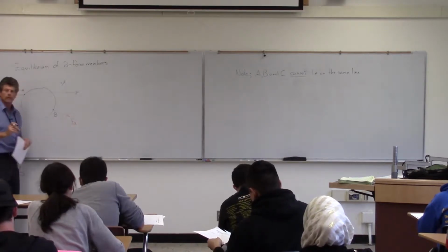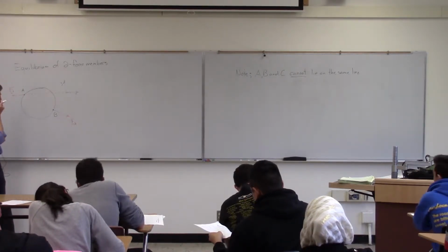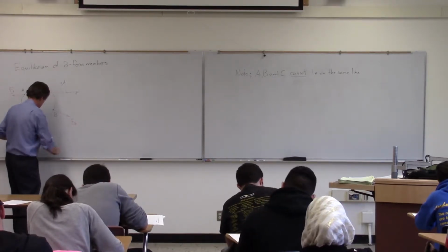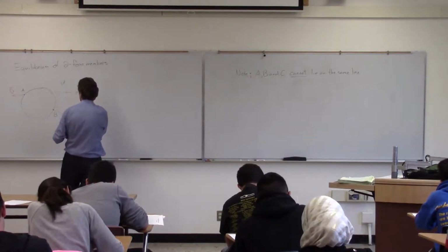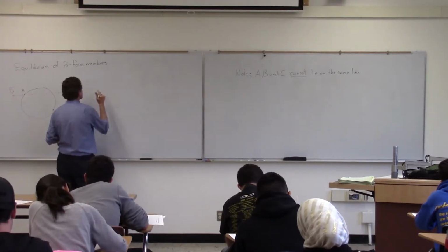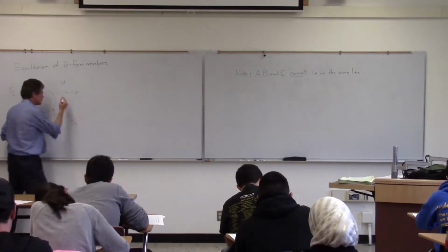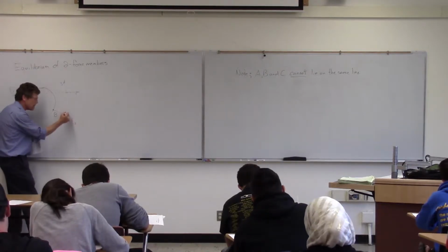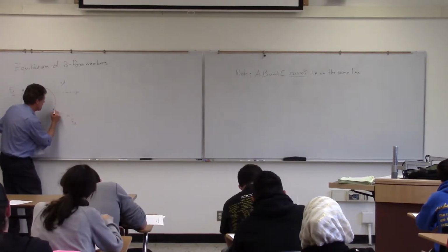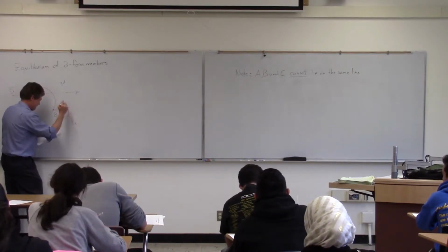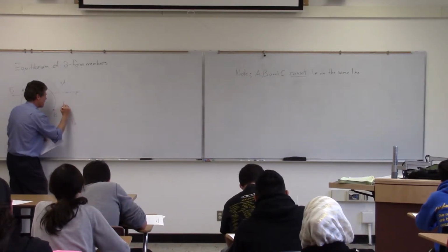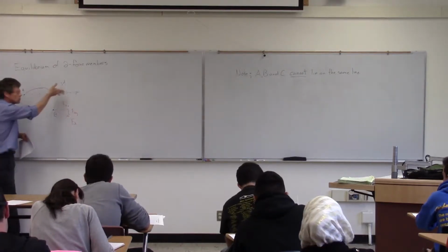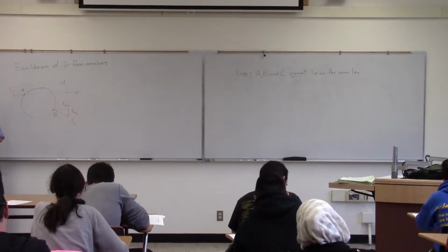Now we're going to put a second force on that member at point B. Now again, since I've got this at point B and I've described a coordinate system like that, I can break my force 2 into components that are consistent with that coordinate system that I've established there.